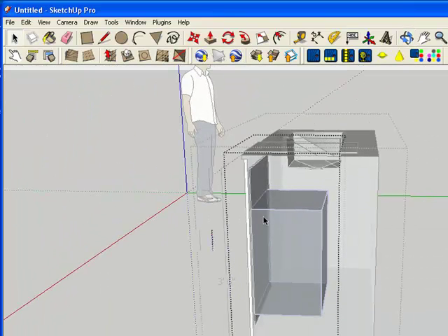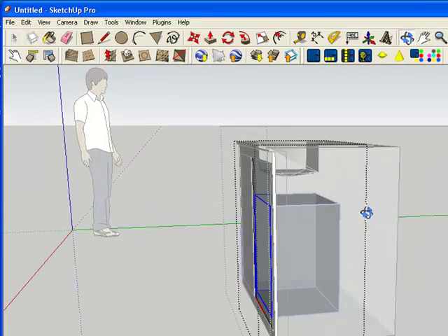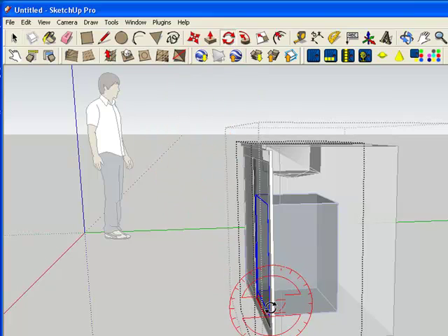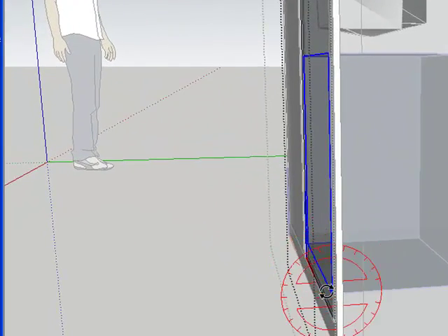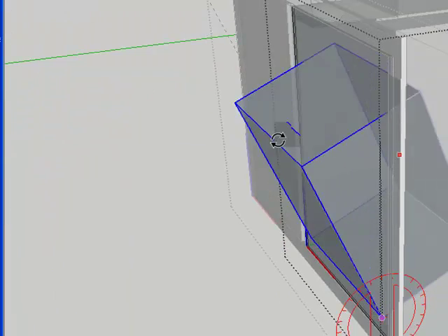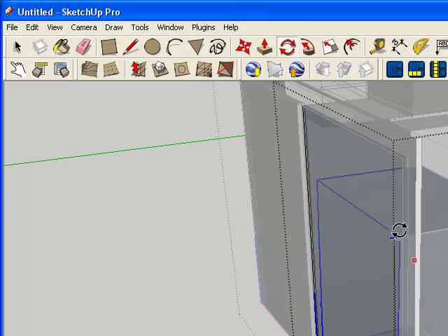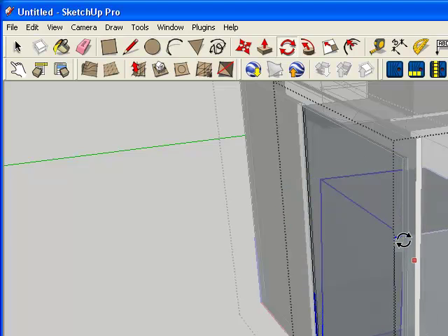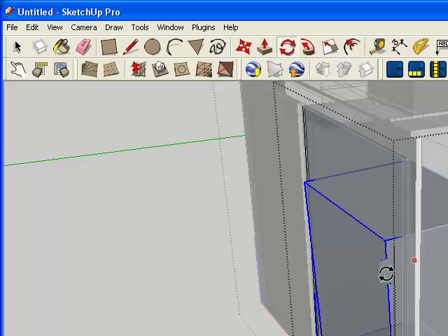Now, of course, if you've ever had a bin, you know this really would have to be a curved surface. But see, by trial and error and using this experiment method, we can see that. If I come down here now, click on this, come up, catch this, and then rotate my drawer out. Oh, wait a minute. It's going to cut right into the top of the thing. So I can figure out where I would have to make my bin and what curve I would have to make sure that the curve of the bin would come out through the opening of the door.